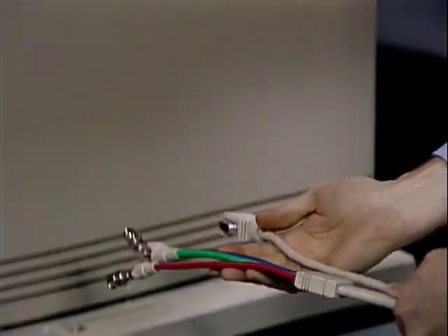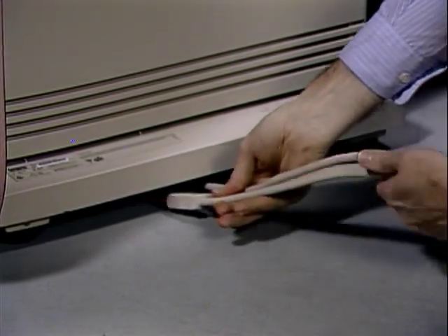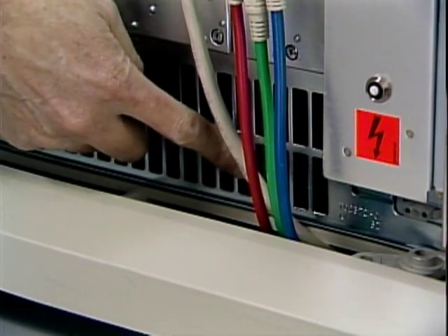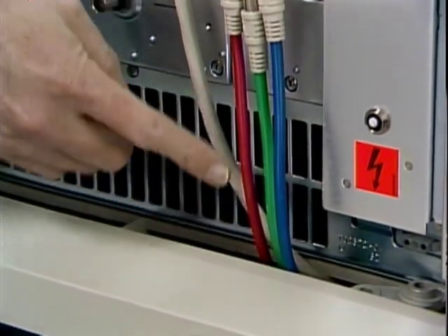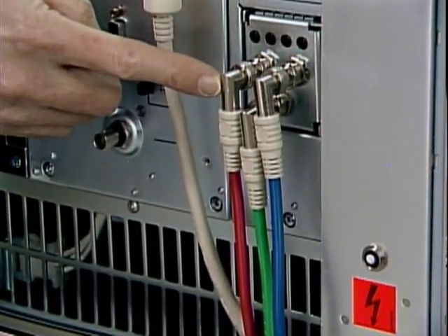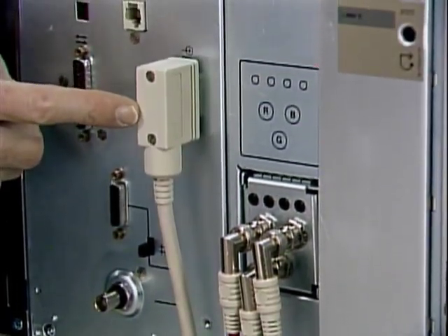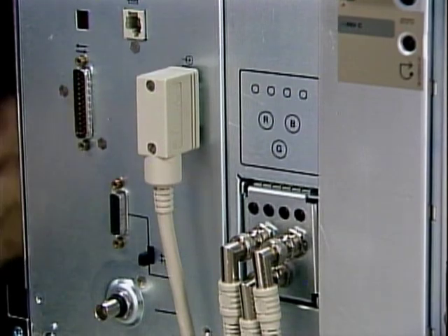Slide the system unit end of the video cable assembly under the back of the system unit and pass it up through the opening between the metal chassis of the system unit and its plastic base. The signal cables attach to the matching connectors on the graphics cover. The keyboard pointing device cable connects to the I/O cover module.